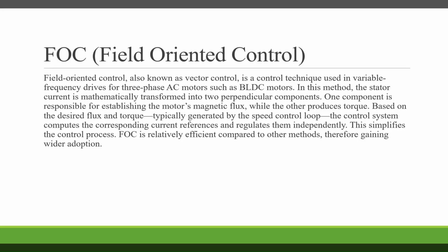One component is responsible for establishing the motor's magnetic flux, while the other produces torque, based on the desired flux and torque, typically generated by the speed control loop. The control system computes the corresponding current references and regulates them independently. This simplifies the control process. FOC is relatively efficient compared to other methods, therefore gaining wider adoption.